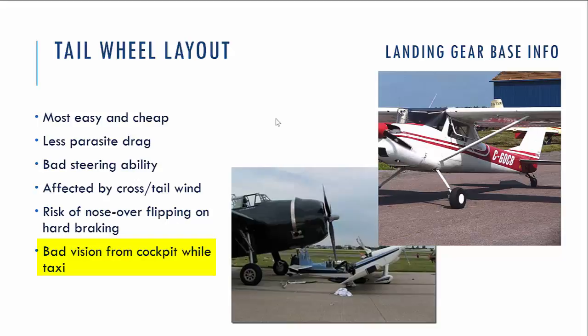You have to perform some S-turns to keep the taxiway in front of the aircraft clear, or you have to use the help of ATC or other observers on the airport to keep the space in front of the aircraft clear.